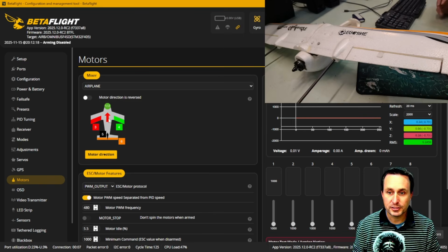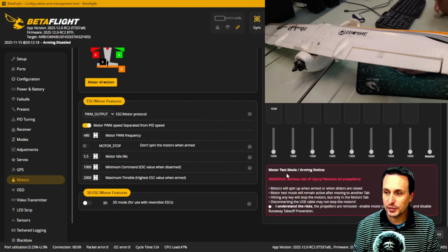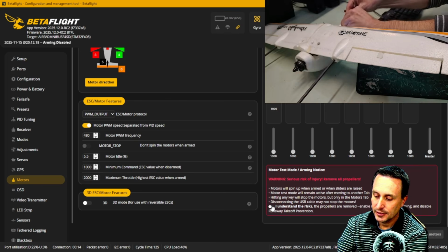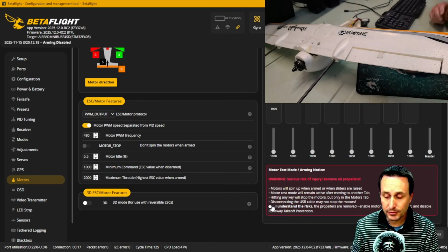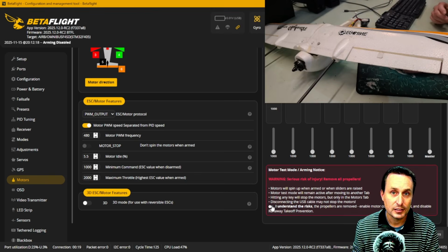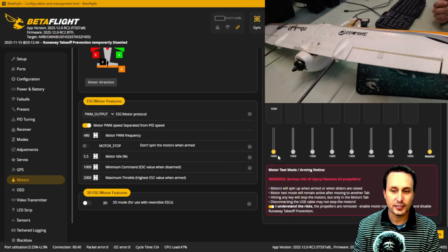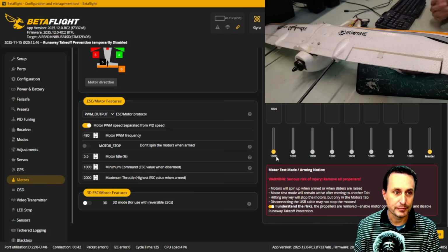So with this mixer set, the first thing we can do is check: does our motor work now? So I'm going to go ahead and plug it in, and you should hear it. Dun, dun, dun, dun. It should give a power up like the ESC will normally do. I'm not sure if you heard that because I have no noise canceling software. And the other thing we can do is just go into the motors tab in BetaFlight like we normally do, and then just move up the motor, and you should see it move. You might be able to hear it, but you can definitely see it there if you're looking right there. When I move this up, it's moving it.